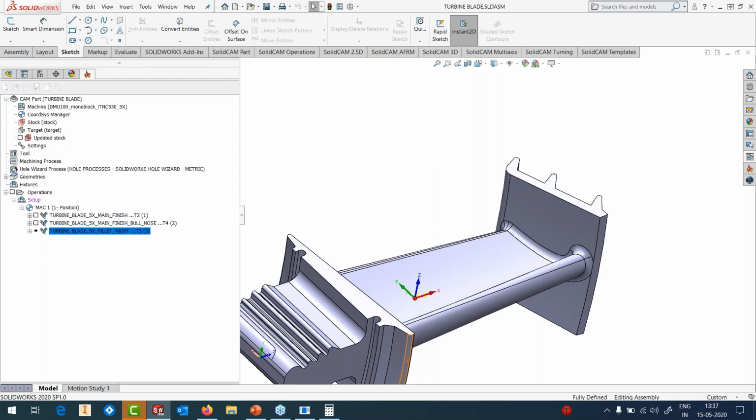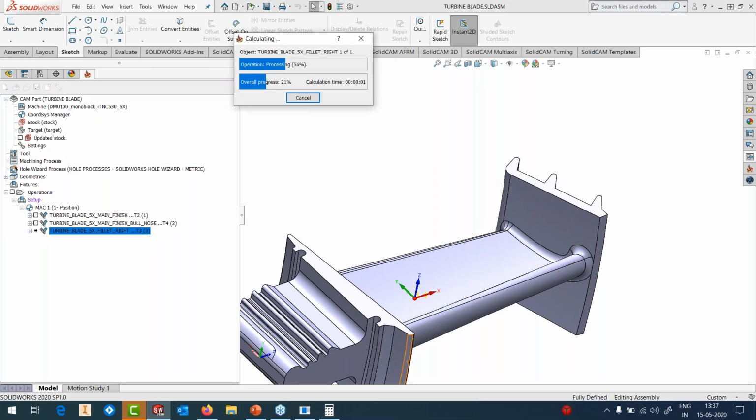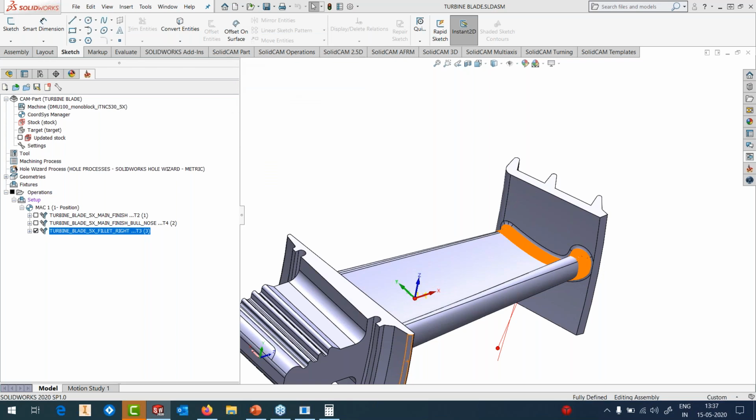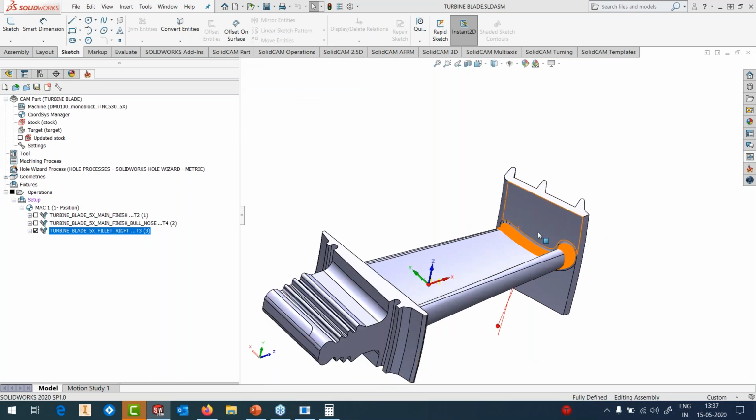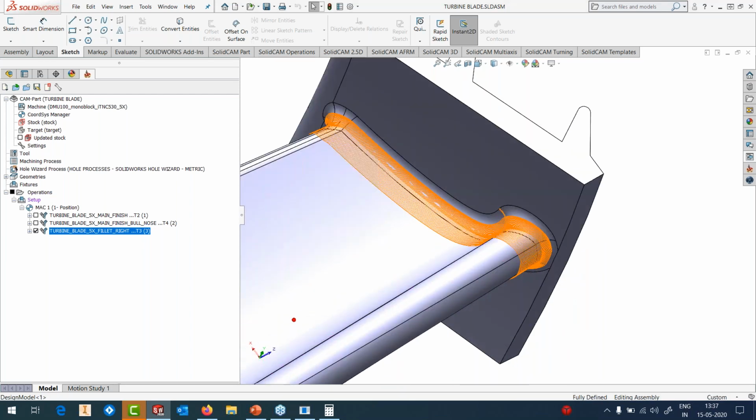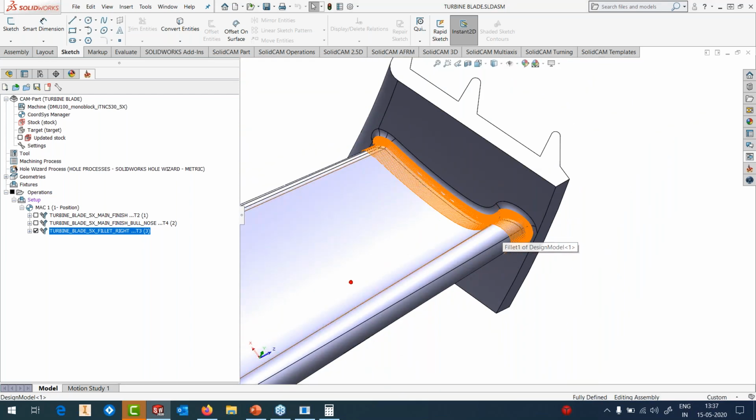The most important part is the creating of proper templates. And by creating templates, you actually end up standardizing your toolpath generation. So a senior most person can put all the experience that he has generated over the last several years into effective templates, and the engineers below him only have to apply the template and select the right geometry. Okay, the toolpath is done. Again, looks nice and clean.